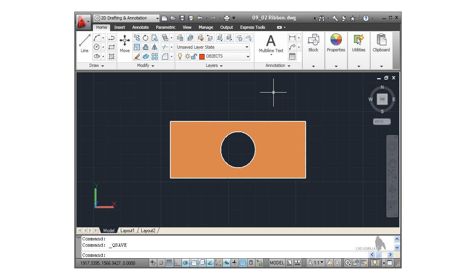When you first install AutoCAD and run it for the first time, you'll be greeted with the ribbon interface. This is the area at the top of the screen, and as you can see, there's the Draw panel and the Modify panel there, for example, and they're in the Home tab there on the ribbon. Now, the ribbon itself is part of the 2D drafting and annotation workspace.